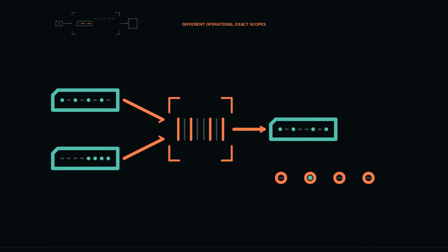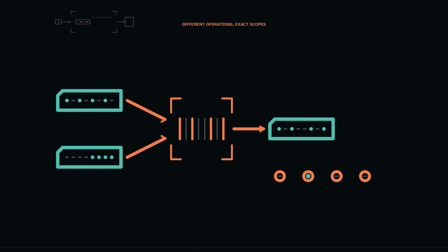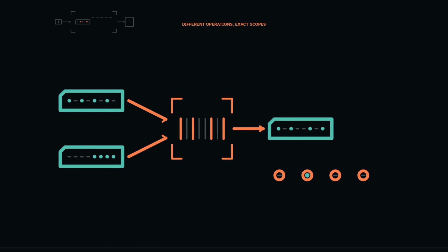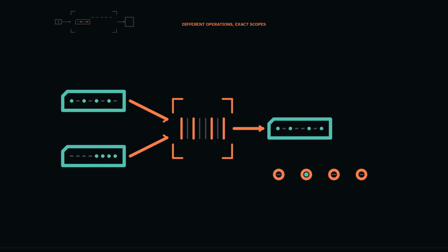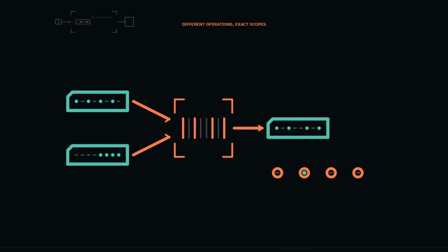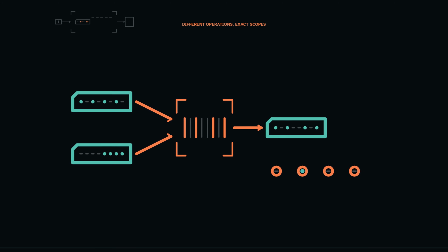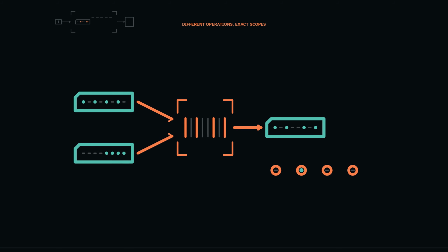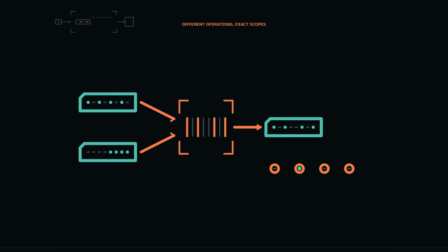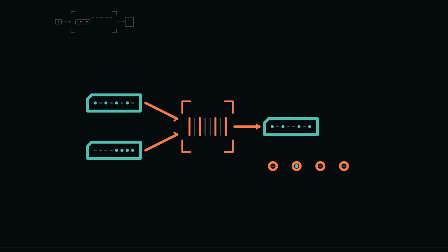Predict one unseen result. Hexadecimal AA is 10101010. Hexadecimal 0F is 00001111. Exclusive or produces 1 where the aligned bits differ, so the result is 10100101, hexadecimal A5. Because the result is not 0, the 0 flag is clear. Its highest bit is 1, so the negative flag is set under SE8's flag rule. Logical operations clear carry and signed overflow. Those flags do not retain facts from an earlier addition.